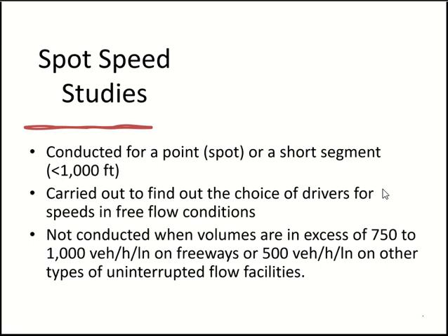Less than 500 is free flow in all cases. Clear? So 500 is for smaller roads, like 2-lane roads, where 500 is good enough. But if you have bigger, major highways, then you can even go up to 1000, no problem. So you can call it free flow.